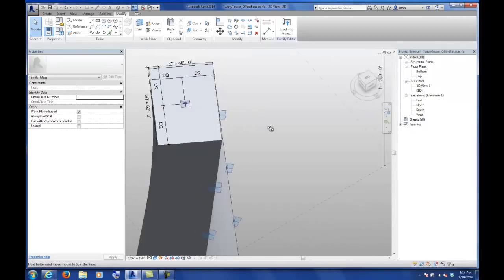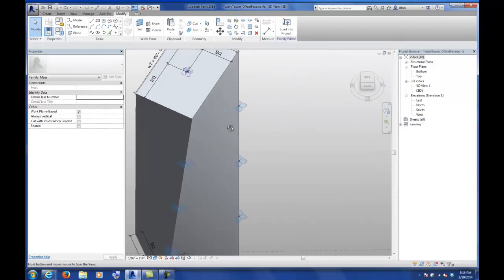So what I'm going to do is create a couple offsets, and then we're going to create another particular surface. Now, one thing that Revit doesn't have that Rhino has and does really well is offset surfaces. You can create whatever form you want and then offset the surface. You can even get into Grasshopper and do all that. In Revit, I do have an offset option, but I can't select anything to offset except for a line. It doesn't do surfaces, so I have to build my offset.